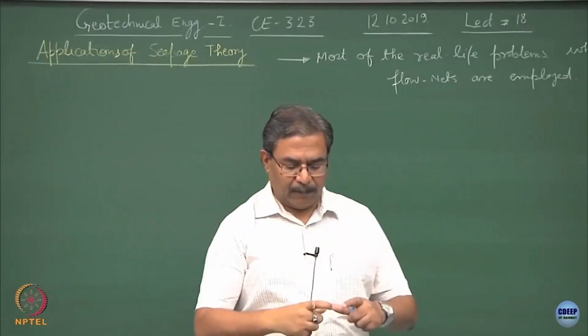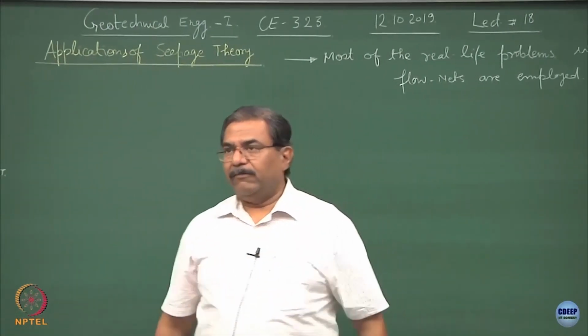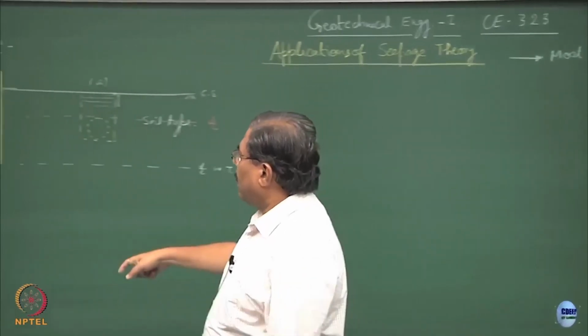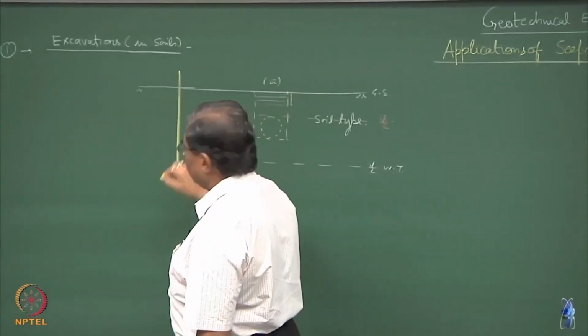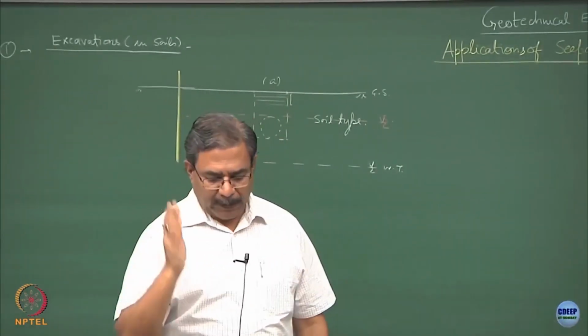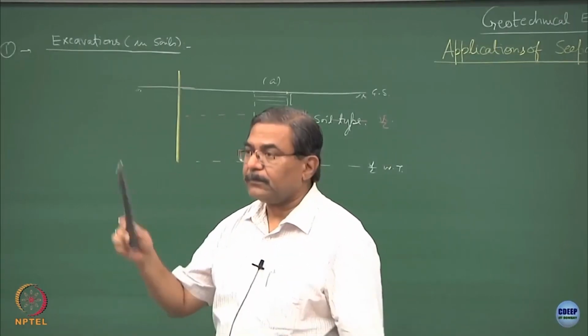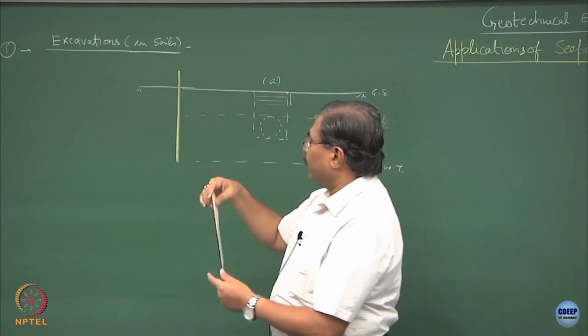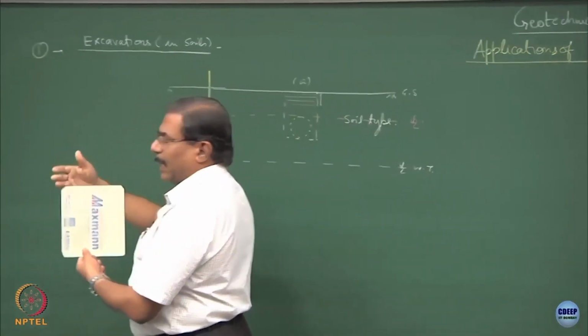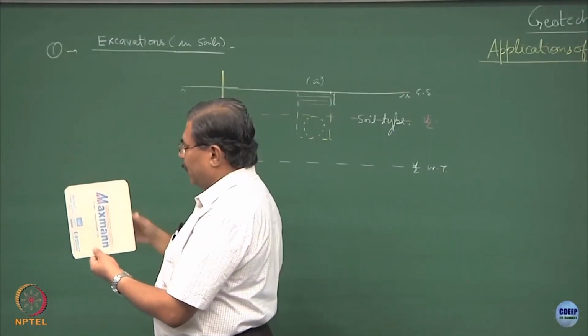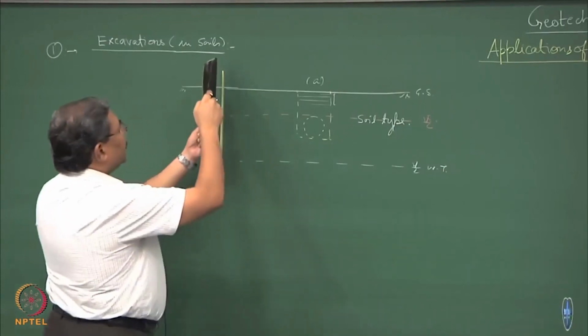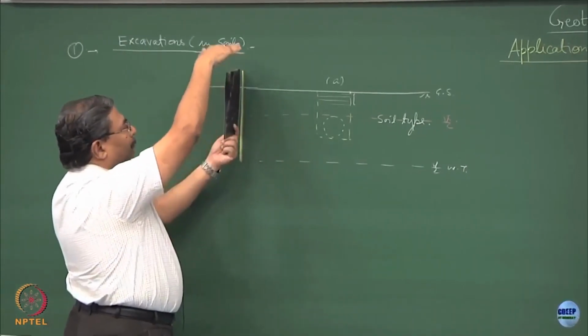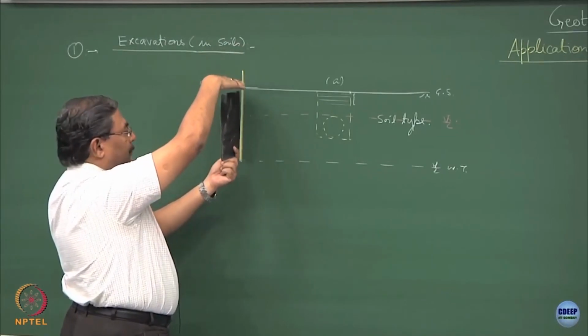So, these are made up of steel, very stiff steel. There will be a cutting edge at the bottom, and these are 2D elements like this, made up of very high stiffness steel. So, what we do normally is of certain size and shapes and the geometry depending upon your requirement. So, what I will do is, this element of steel I will tamp from the top so that it goes inside.